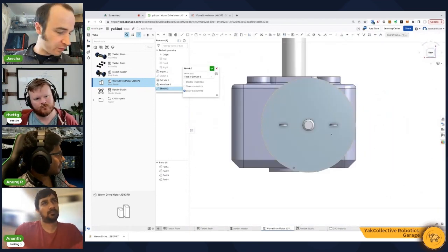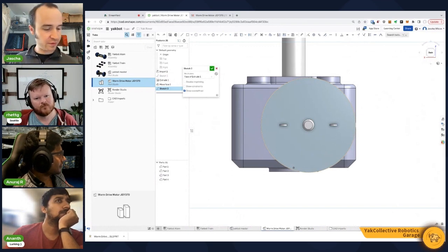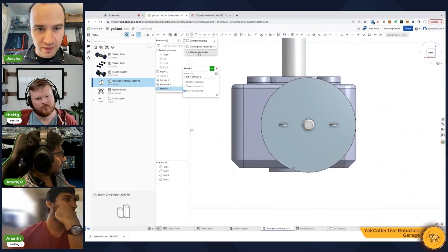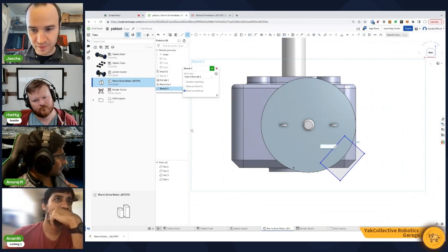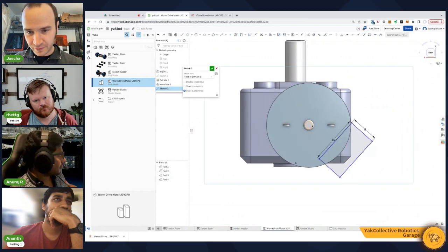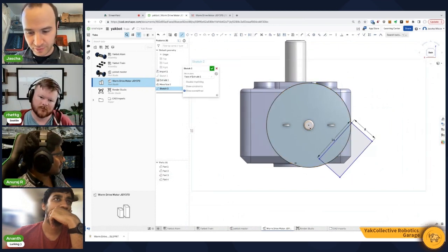And then just volumetrically, here I can also add, real quick, it's usually very important to add the connector. So let me really quickly add this connector. It's at a 45 degree angle. It's 14 by 8. So we will do an offset rectangle like this. And this is 14 and this is 8. And then we need to use the center point of this circle to reference a 45 degree angle. Make that a reference geometry.